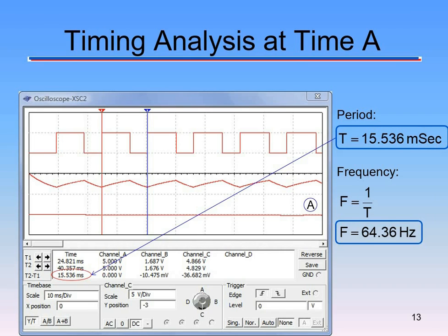So this is time A. We're holding the button down, right? So we're not allowing that first capacitor and the resistor in. We're only using the two that are affecting the clock. So the clock signal remains the same. You see that? The output of the clock, it's the square wave at the top. So as the capacitor discharges, we're at 0. Capacitor charges, we're at 1. So that's what it's doing there. It's going to do that forever. Just up, down, up, down, up, down.